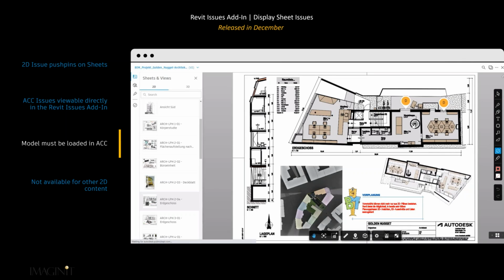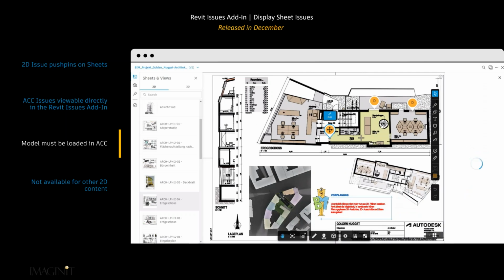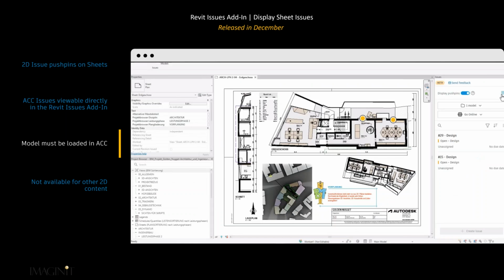So when an issue is created, again, in a sheet view of the project, and this has to do with Revit. So we've got our published sheets from the Revit file. When an issue is created, it does link here. So we're seeing in Revit, we can navigate through our issues. They show up within our Revit file, and we can review the status of those issues. And you can see you have the same inputs for the issue that you would in the